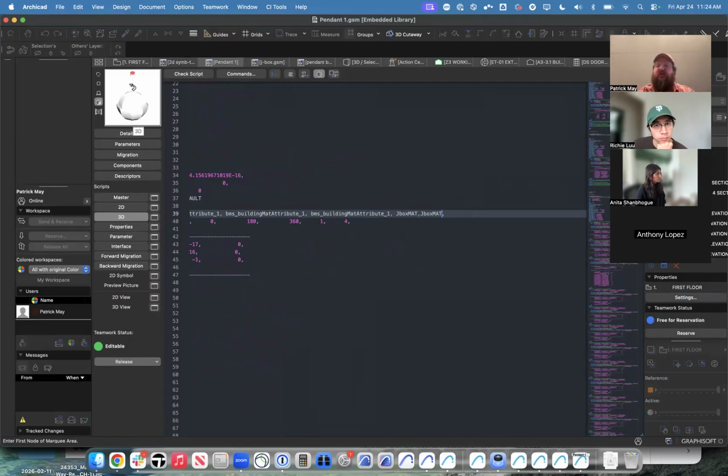Unfortunately, you will have to kind of parse together these attributes. Because they're all being saved individually, it's going to default to everything as material attribute one, material attribute three for each of the individual objects that we're combining. So unless all of them have the same number of attributes, and even then it might decide that white is going to become red and red is going to become black when you combine these objects together.